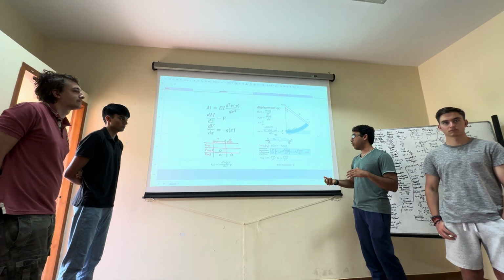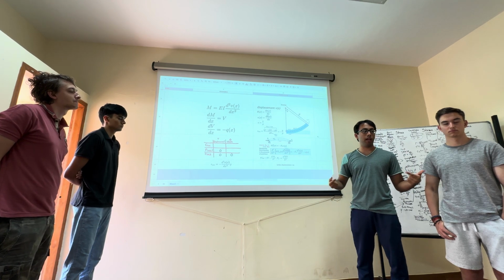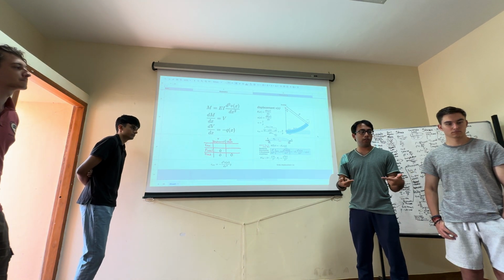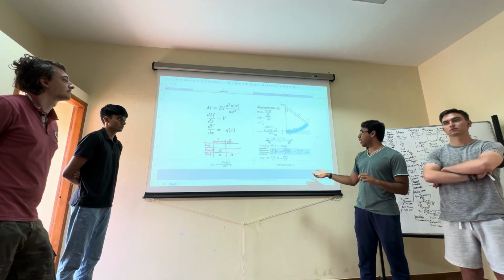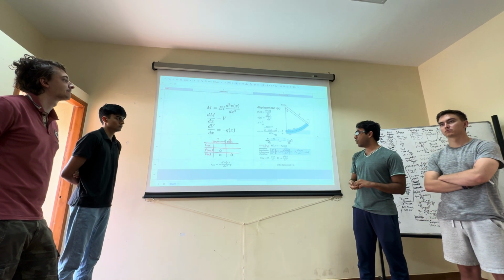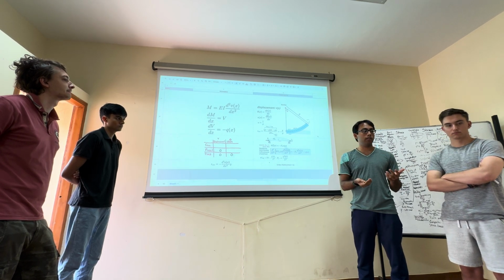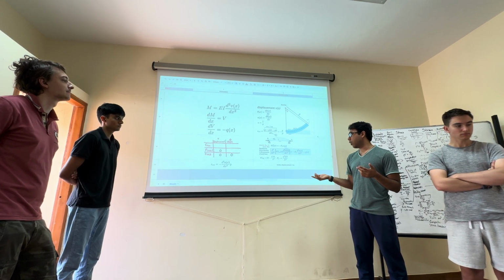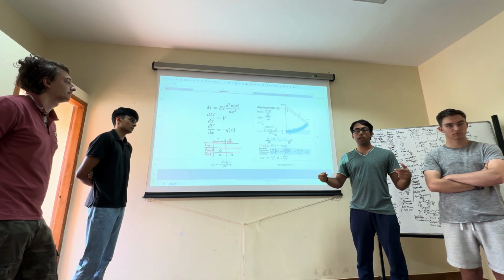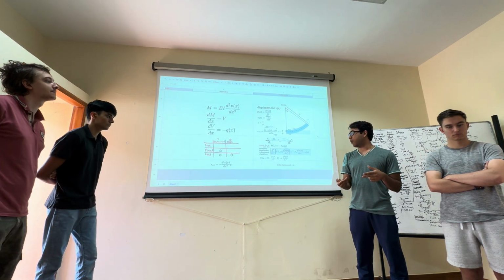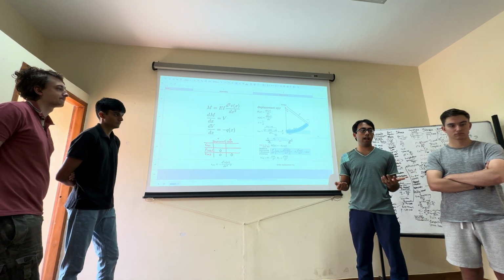So if you have a rod that's already bent, applying an additional axial force along those two ends will cause additional deformation. You'll see the equation, while it is similar, has additional terms. And what's interesting to note here is that we have this new term where it's the elastic modulus times the moment of inertia or moment of area, I effective. And this is like an effective version because when you're putting a load under compression, the stiffness does decrease. And so that will affect how the deformation acts.